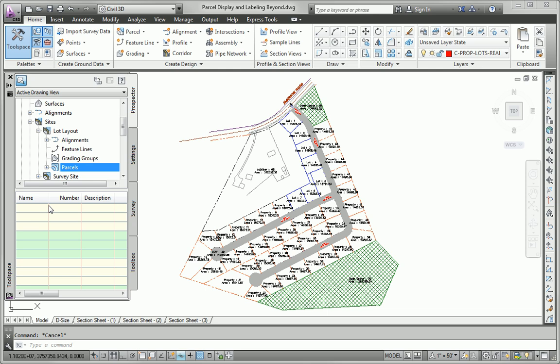What I would do, if you could just imagine a list of parcels here, they would be arranged maybe by name or in the order that they were created. What I would do is scroll over to this column called Style, and I would click the Style column heading, and it would sort them by style. And all of the ones that have the style of Property, which is everything left that I need to stylize, would kind of all group together. And then I could go through and use my Shift key and select all the ones that have the style called Property. I could right-click the Style column and hit Edit, change it to Lot, and it would change all the parcels at once. So that's how you would normally do this. But we can't right now.